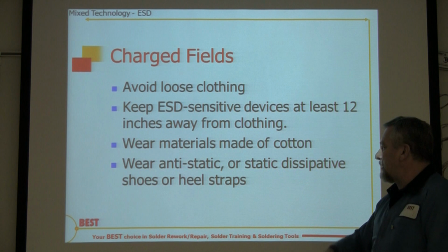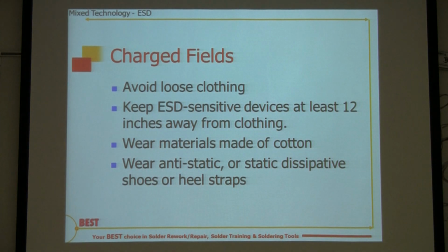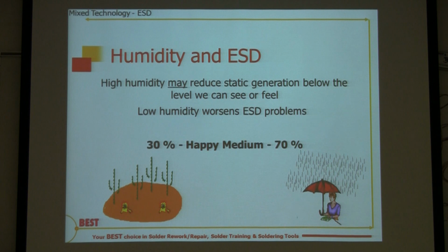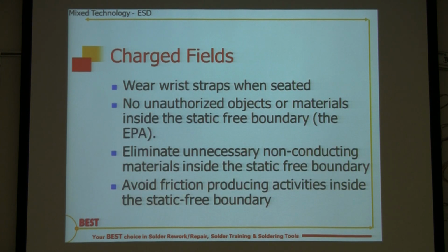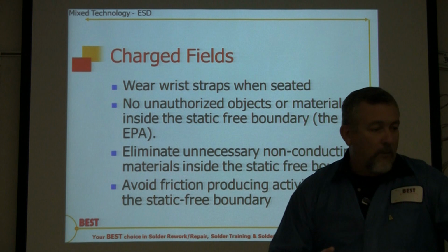Wear static dissipative shoes or heel straps when you're walking around in your workspace. We'll show you these later in the video. Wear wrist straps when seated. No unauthorized objects or materials inside the static-free boundary. Remember what we showed you.